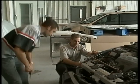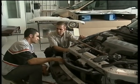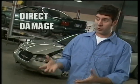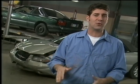Determining damage to a vehicle begins by understanding how the collision occurred. Speak with the estimator or the person involved in the accident to find out. There are two types of damage to look for: direct and indirect. Direct damage is the obvious damage, or the impact zone. However, most damage that occurs in vehicles is indirect or hidden.